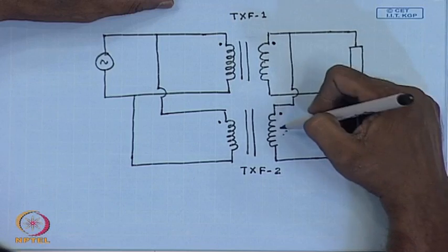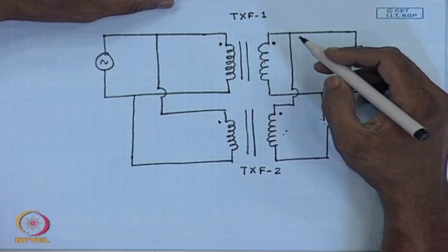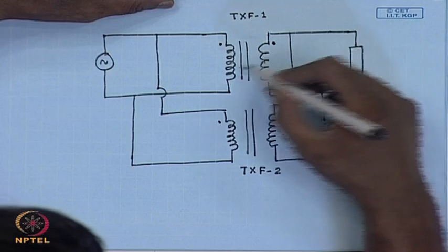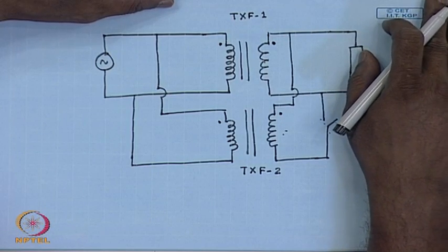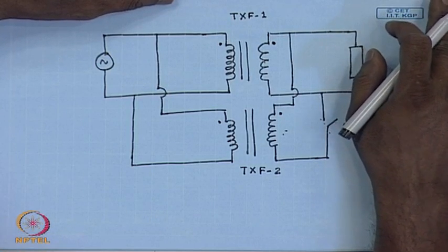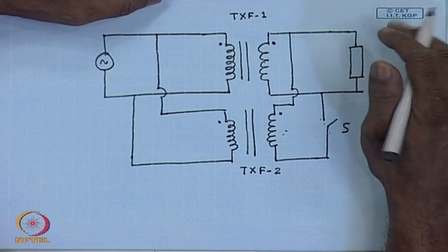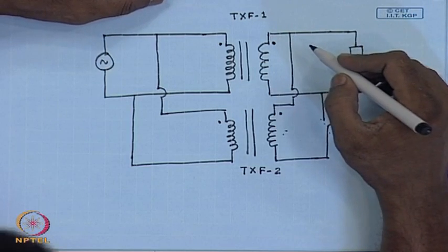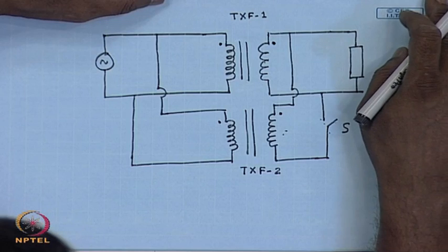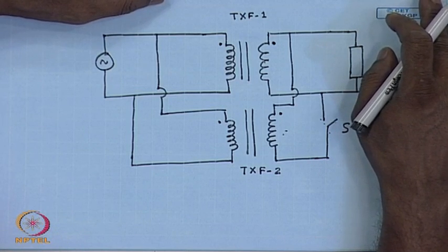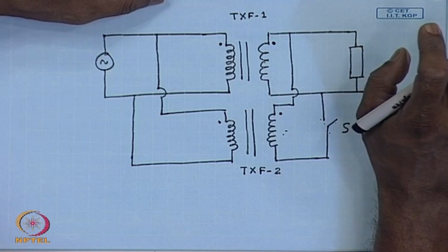So, even at no load a very large current can flow if the no load voltages of the two transformers are very different. So, the transformers to be connected in parallel should have the correct instantaneous polarity terminals connected together, and their no load voltages should be very close, if not exactly equal.